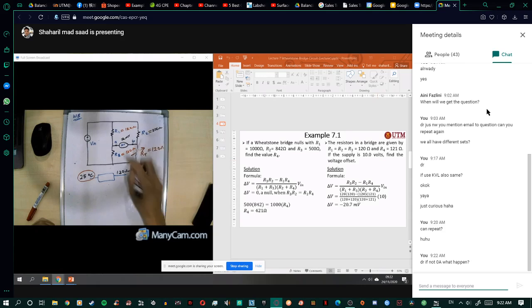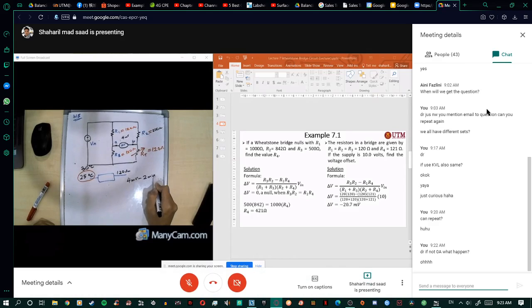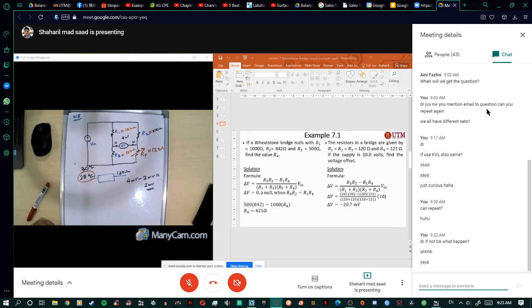So that means after this, if you measure, for example, 30 degrees, and you got about 4 millivolts, the actual value is 4 millivolts minus your offset value of 2 millivolts. Do you get it? Okay. Right. Good.